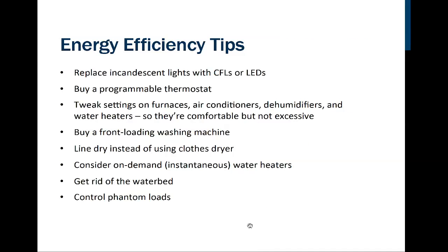Other tips: replace incandescents with LEDs or CFLs. Programmable thermostats are a very smart way to go, because, depending upon how you heat your home, instead of just saving electricity, you may also be saving gas. There are things that you can do to the appliances in your home to make them run more efficiently. Water heaters don't have to get up to 150 degrees. You can actually have them only heat to 125 degrees, and they will do just fine and save you some money there.